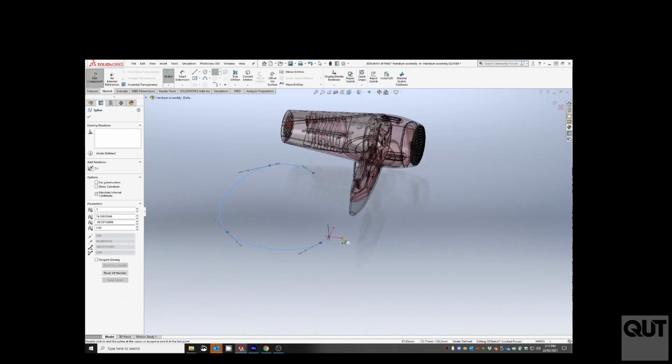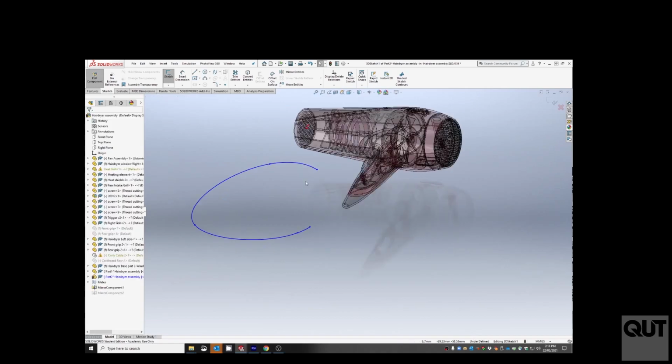keep this curve simple. Don't try to put too many points in there, and don't try to get any sharp corners, because as the curly cable is created, it will intersect with itself and it won't work. The next step is a little bit complicated.